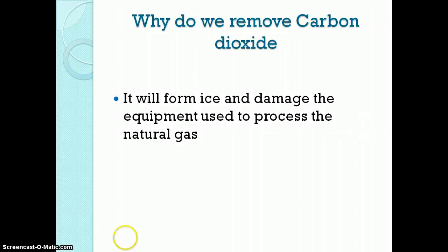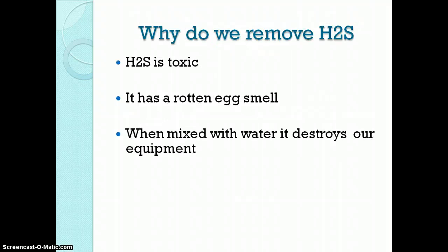Of course, like I said earlier, why do we remove carbon dioxide? It forms ice and damages equipment used in processing gas. We remove H2S because it's toxic and has a rotten egg smell. When it mixes with water, it destroys the equipment.